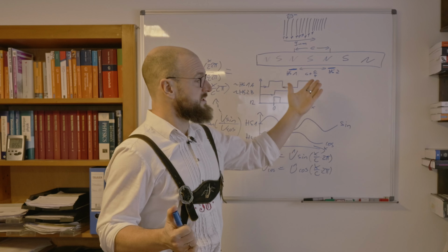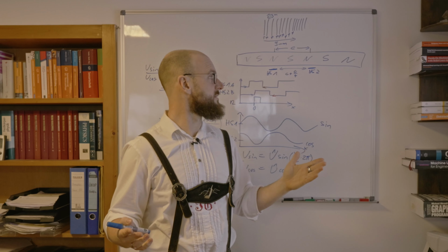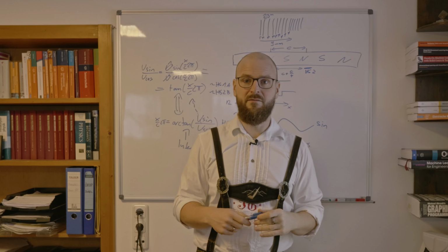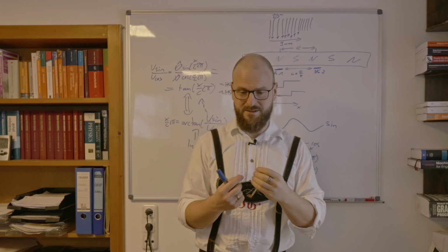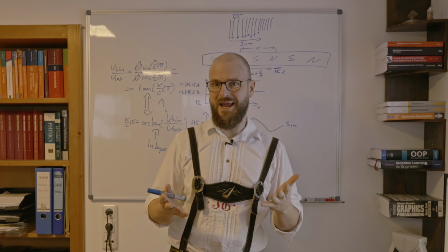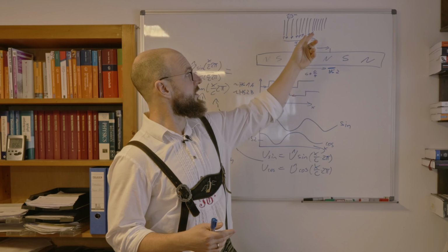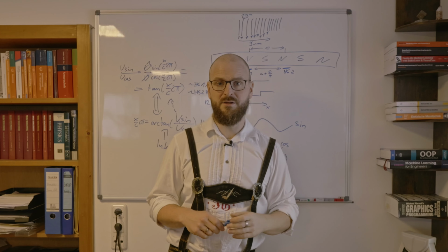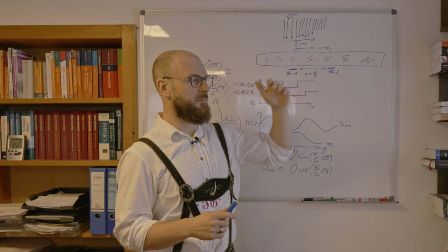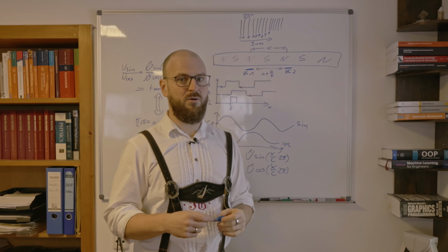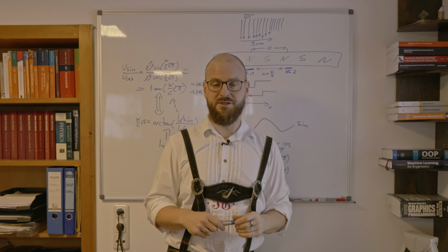Okay, those incremental encoders are used in a wide variety of applications in industry. So for example, those magnetic tapes are very robust to dirt. Yeah, it's magnetic, as long as it's not metallic magnetic stuff, which is the dirt. There's no problem about some dirt, in contrast to the optical incremental encoders, which have some problems with the dirt and so on. But for sure, those have no problems with metallic dirt and so on. So whether to choose which incremental encoder to use depends on the application in industries.